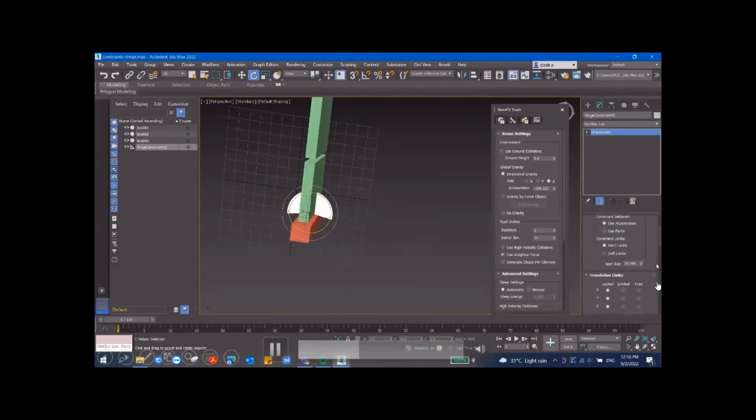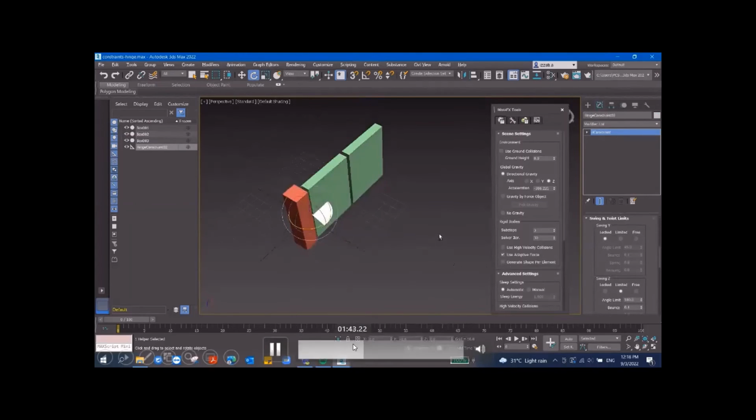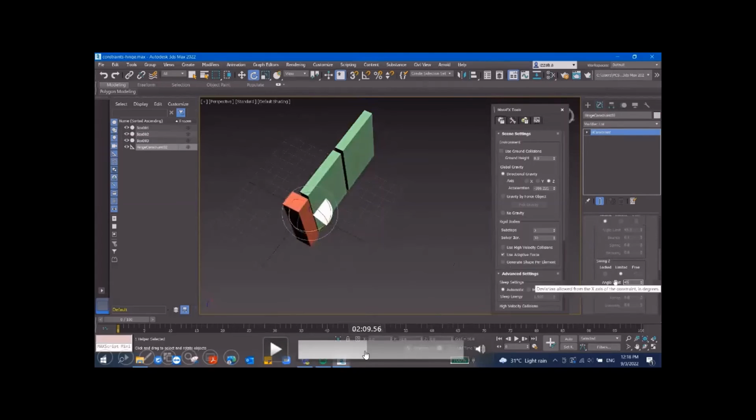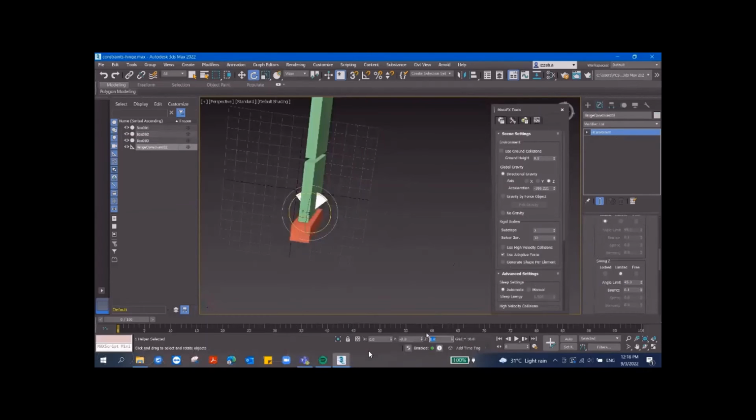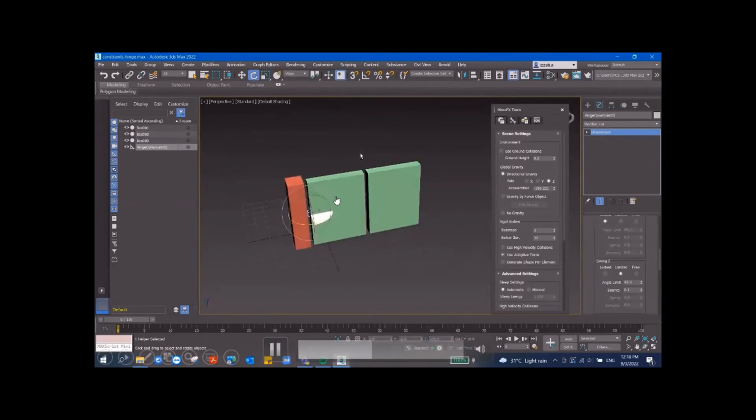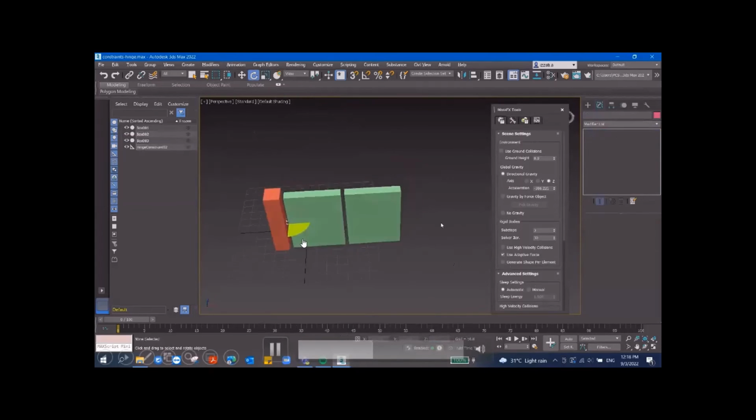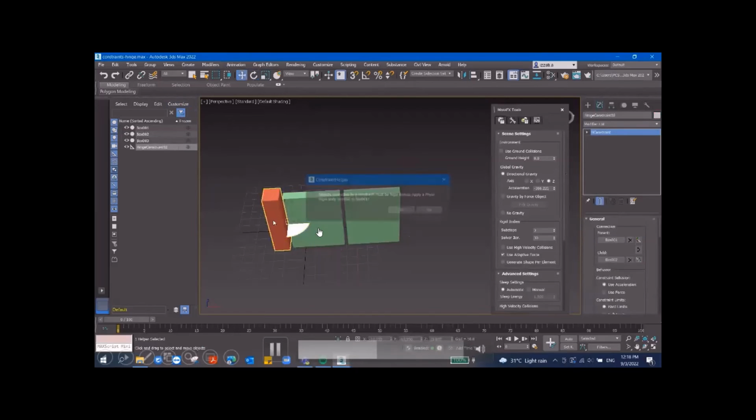If you go to the swing setting for the z-axis, you will be able to change it from here. So let me fast forward. So now I have set it to 45 degrees, and I just want to make it open outside right here. So I've rotated the constraint to be on the outer gate, right?